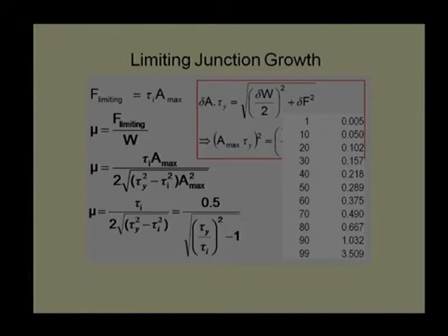We said let us take an example where tau I by tau y is given in some ratio. Let us take tau I divided by tau y as 1% or 0.01. If the interface shear strength is just 1% of the soft material shear strength, the coefficient of friction is almost negligible, it is 0.005.